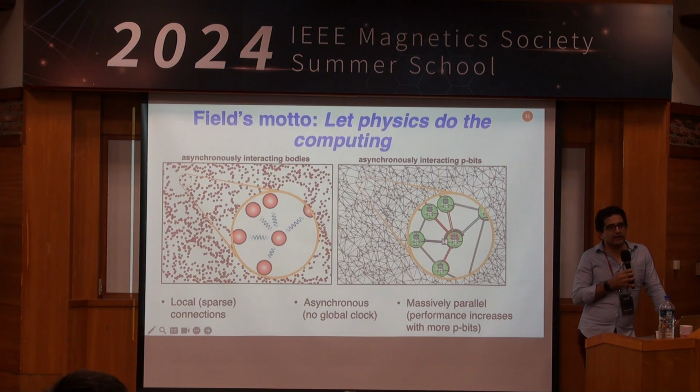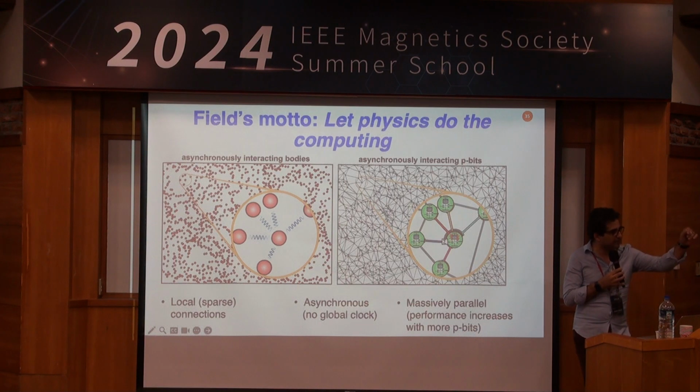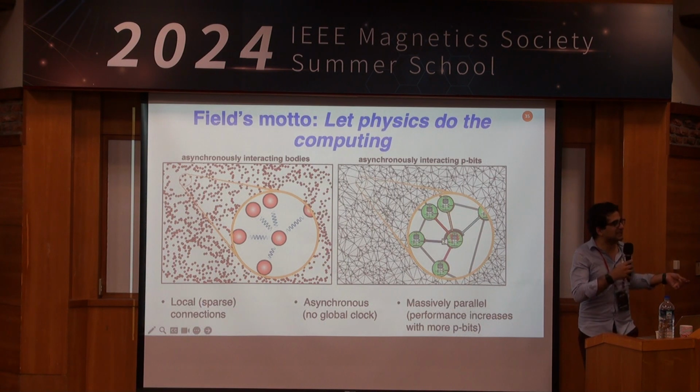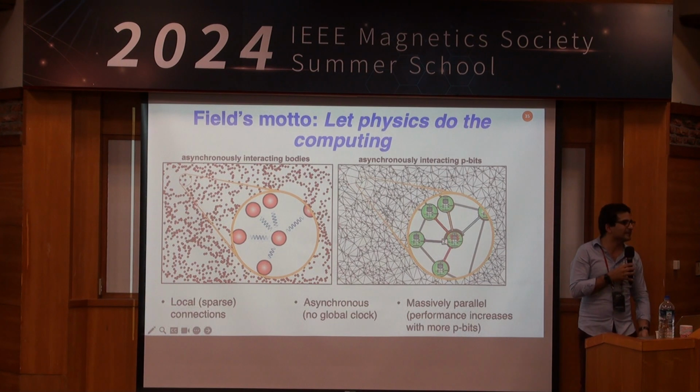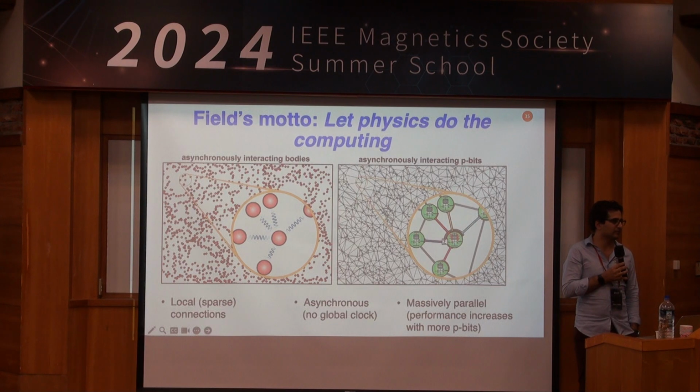Right. Well, if you kill the spin torque, which you can in these double free structures, for example, with no fixed layers, just two free magnets that are fluctuating, nobody can win over the other one, but you can still read the state by pushing a little bit of current, because TMR still exists. But the other idea is to use a very nice MTJ with high thermal stability, and you just need to set the write current to be 50%.